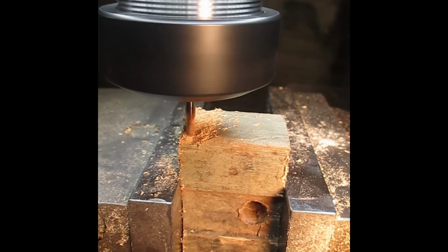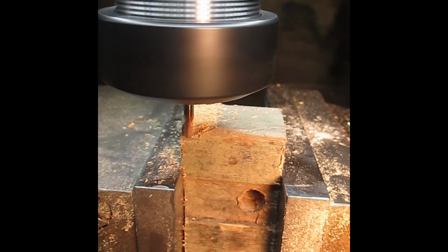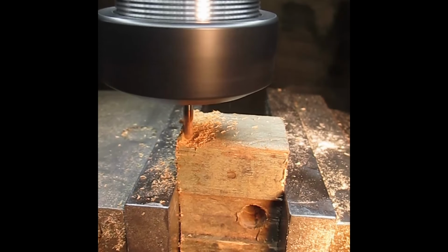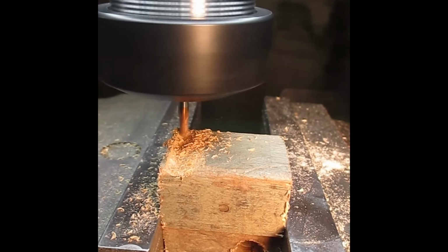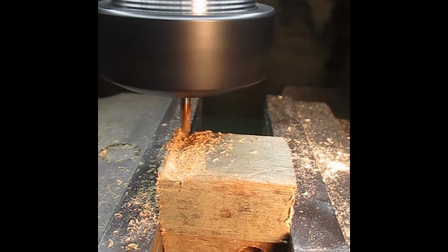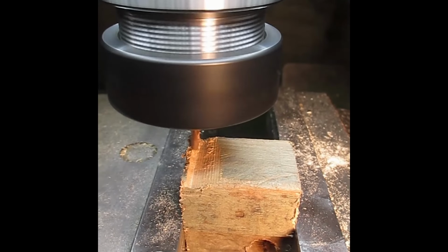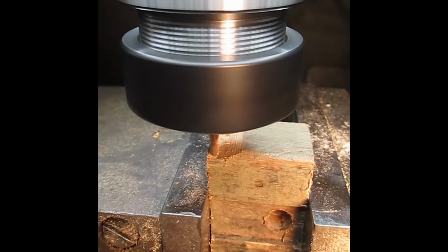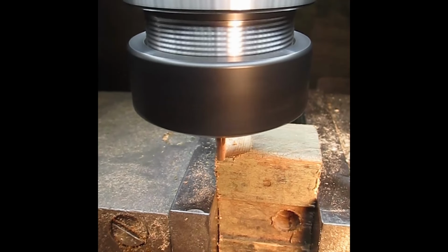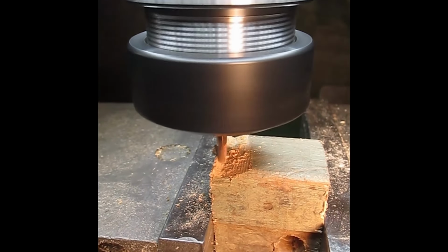If I go the next step and create a slot with this infinitesimal cutter, I would create a one-dimensional line. And finally, if I was to create a pocket with the pocketing canned cycle, I would be doing the same thing in both x and y directions and do an area. In every case, the depth is set constant, and that's why they call this basically 2.5 dimensional machining.